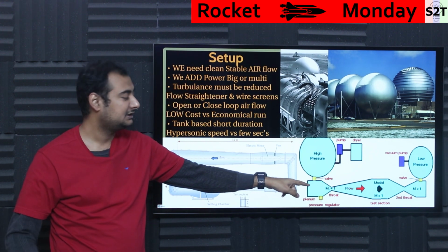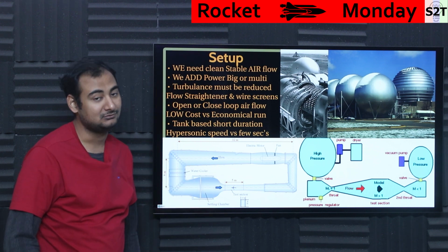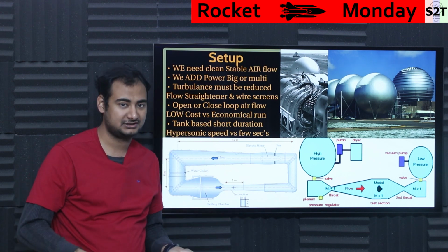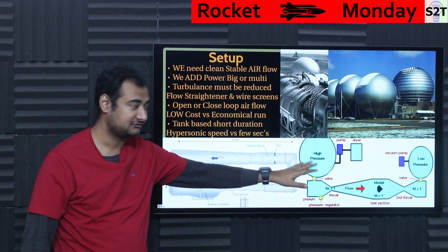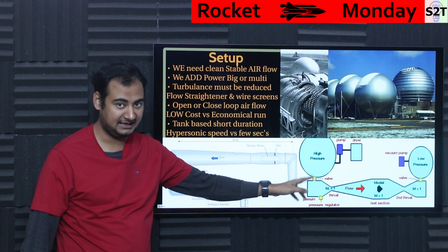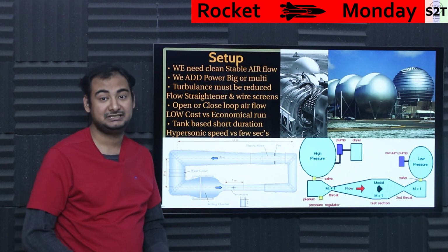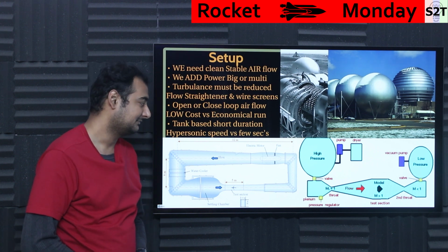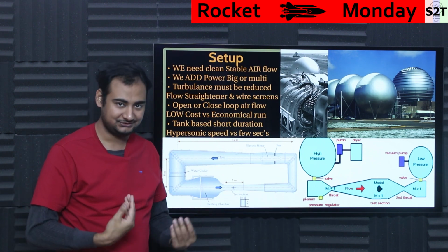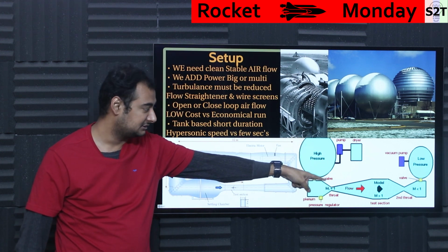Now, there is an issue: if you expand high pressure gas that quickly, you may cool it down too much. It's almost like how rocket engine exhaust is very hot when it's going through the throat. The moment it expands, it cools down. If you have high pressure gas which is not a reacting gas, you could cool it down so much that air liquefies here. So you may have a heater added here just to make sure that air does not turn to liquid nitrogen. So they may need to heat it up to, let's say, 900 degrees Celsius. Again, be mindful, that's how we liquefy air. We compress this puppy and let it expand. That's what you're doing here. So you do need to add heat. So at that point in time, you get your hypersonic flow. Everything is awesome. Then you'll send it to another choke area.